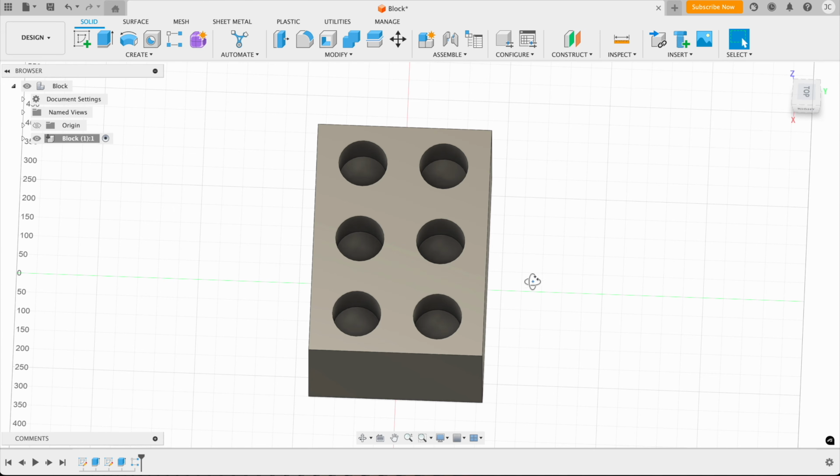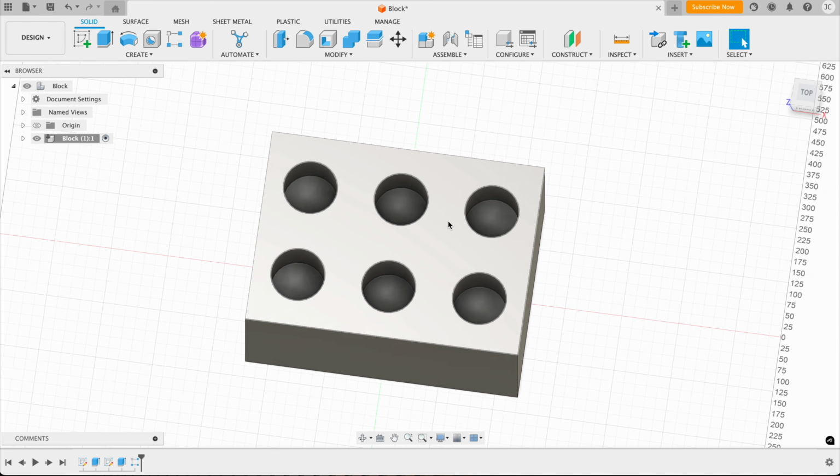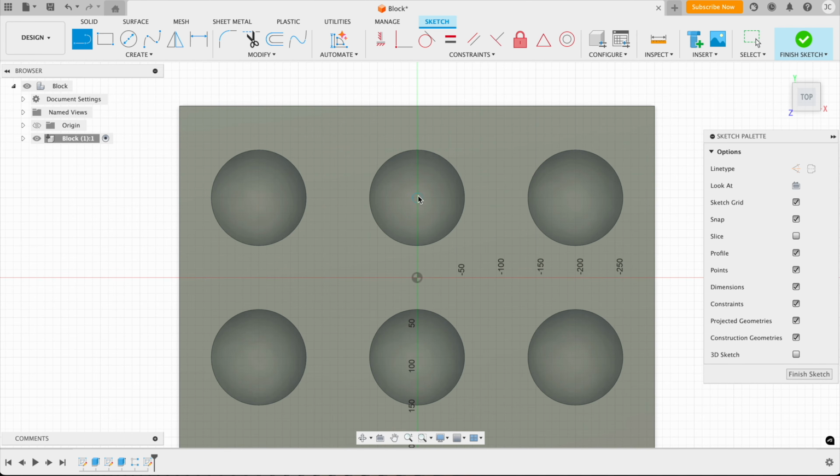And now there's another thing that I want to show you with cutting. So let's say that there's more detail in this. For example, if you click on a surface, click on Create Sketch, then click on the line tool to start drawing a line. So what we want to do is draw from the center, and this is going to be 90, and then hit Enter. And then we want to hit X again on the keyboard to make this a construction line. And then we want to draw a circle of 25mm and hit Enter.